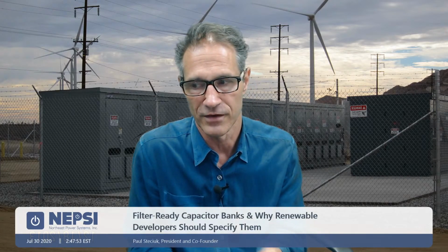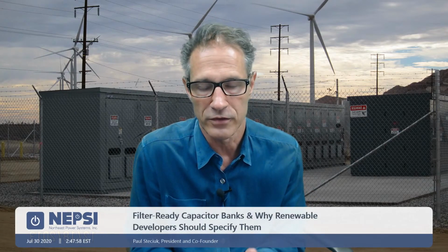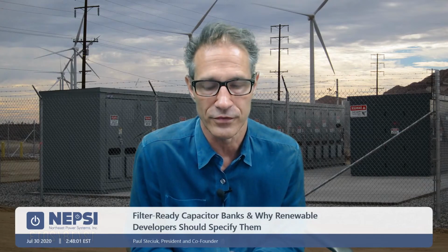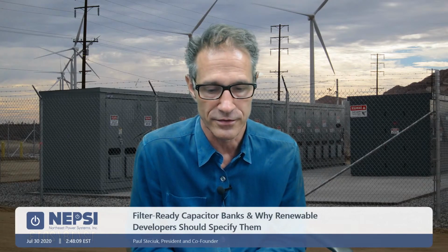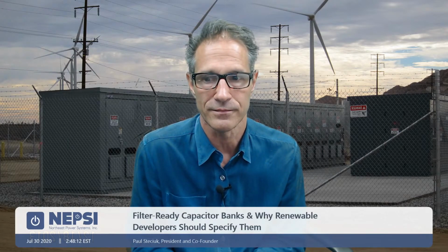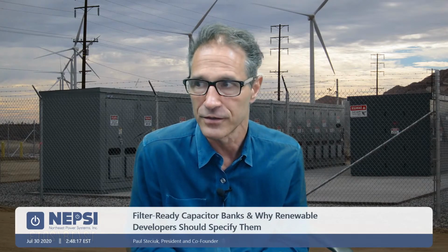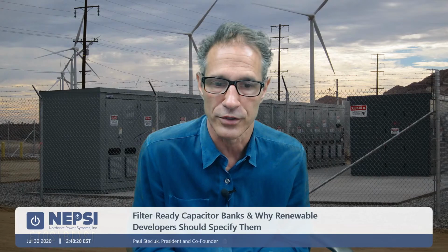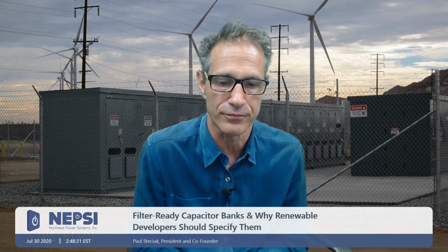It's going to be a very conservative result. In fact, it's going to be able to drive a lot of current. So modeling voltage sources within your harmonic study is very tricky. If you don't have a value, then consider maybe 1% maximum. Transmission level distortion tends to be lower than that, even lower, so maybe 0.5%. It's a tricky question. What you know is also very tricky, and how you do that modeling is tricky. So it could easily force you into a harmonic filter by modeling that primary side voltage source.